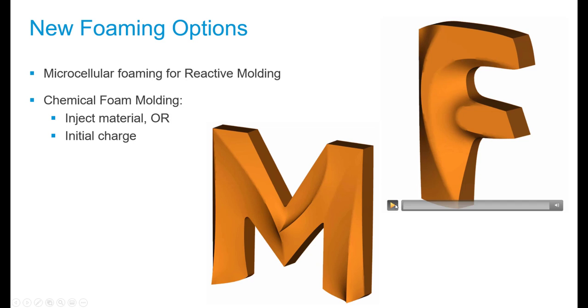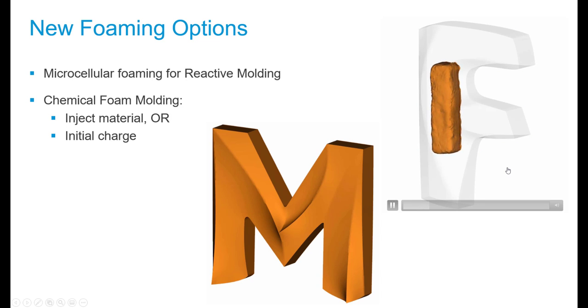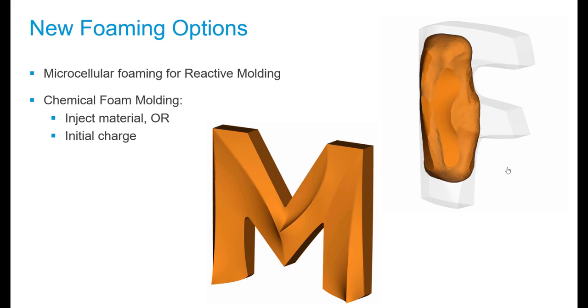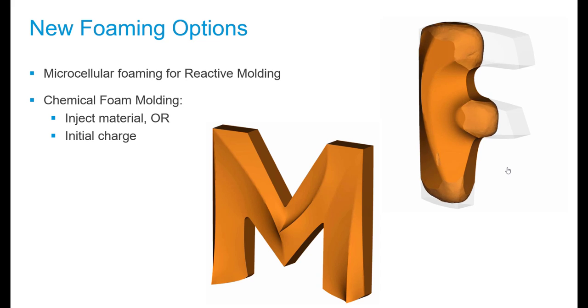Or you can specify a location where you say, these elements over here are initially filled with foam, and now the foaming reaction will start and fill out the cavity. So either through an injection or an initial charge, you can start the foaming.